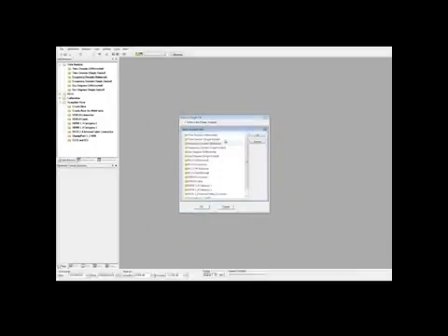And open that up. Now, instead of opening it up in the frequency domain balance like we did before, we can scroll down and open it with the CEI insertion loss and insertion loss deviation template that we just programmed from that MATLAB script.